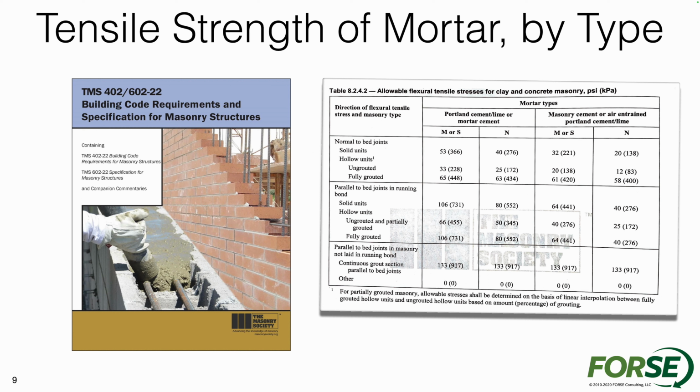We're going to see some of the properties here reflected. Mortar cement a little bit better again for those higher seismic areas. Also, having a higher tensile strength, which makes sense. And then the masonry cement, which is going to be more common, having slightly lower tensile properties. Again, this is going to be important for higher seismic areas, but it'll also be important for an unreinforced masonry system.